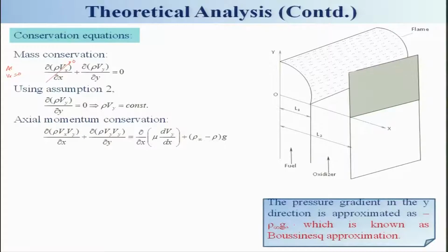Keep in mind that we are not considering the buoyancy effect, therefore this term will be 0. And as Vx is 0, this term will be 0, and this is the inviscid flow, so this term will be 0. Since ρVy is remaining constant, this also will be 0. So, there is no need to solve any momentum equation as such.